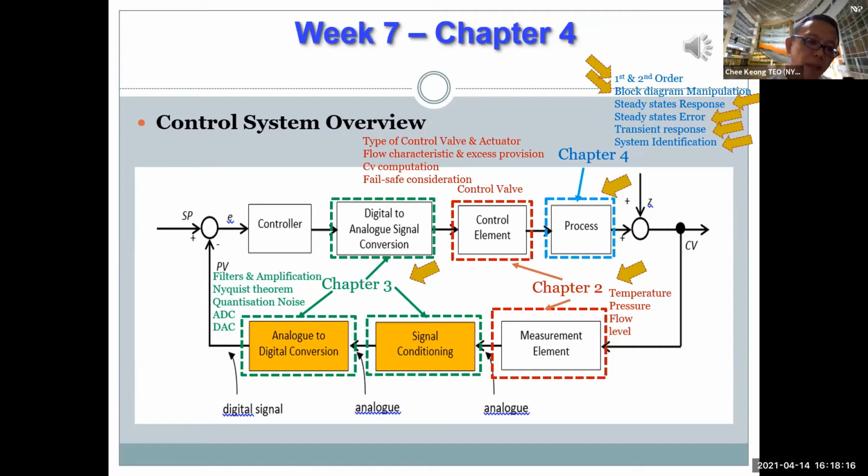And then lastly, the quantization, whether you use a half LSB or full LSB kind of quantization to convert your data into the actual binary equivalent. Then we talked about the DAC, where we look at the lookup table, find the actual analog value for the digital equivalent, construct your step function, and then do a filtering. So that is basically chapter 3.